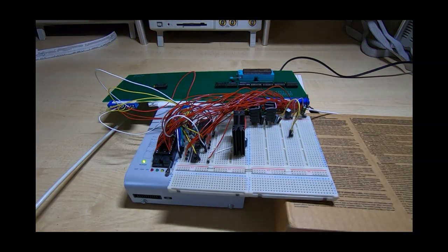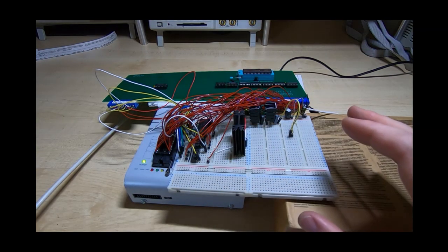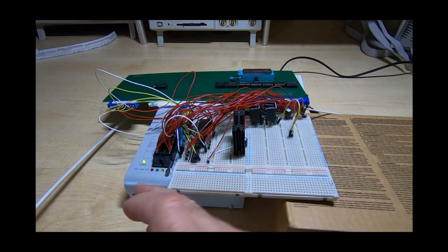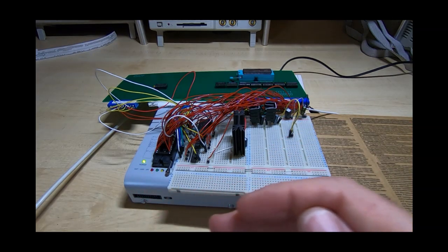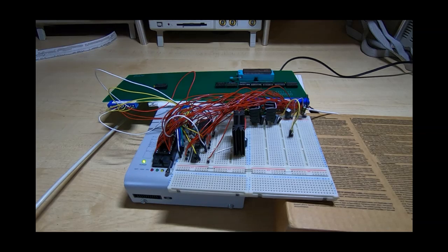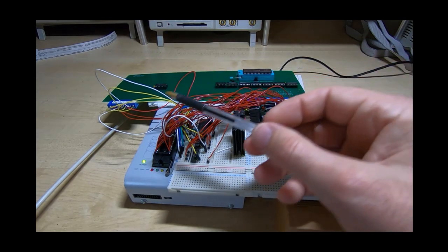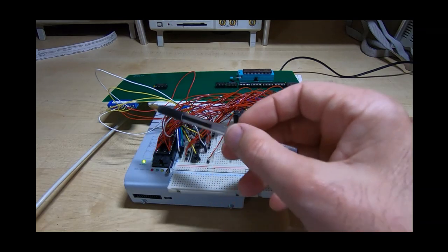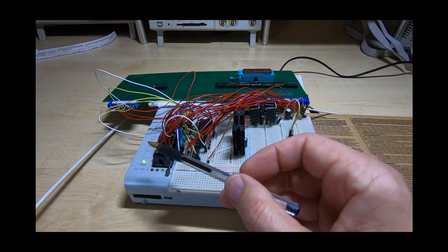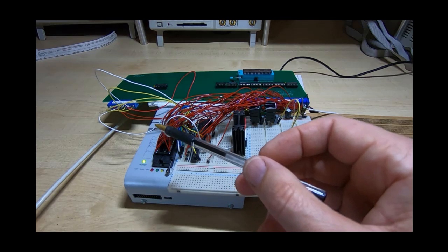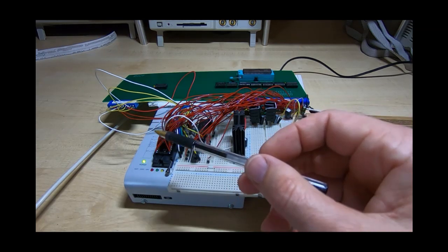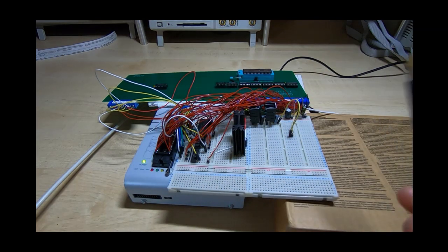Also, if you recall, the way I have this configured is all the address lines from the programmer are shifted up 2 places. So instead of the address lines on the jig starting at address line 0, 1, 2, 3, etc. on the programmer, they start at address line 2 and run up through 3, 4, 5, etc. upwards.